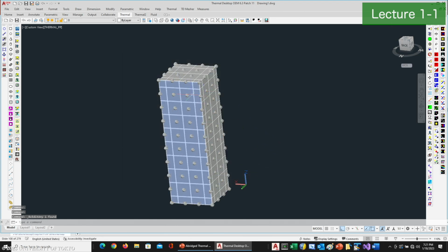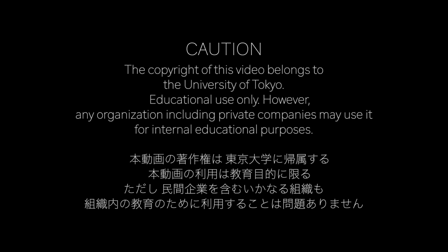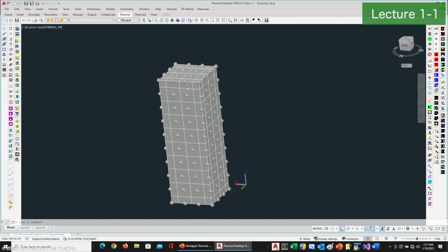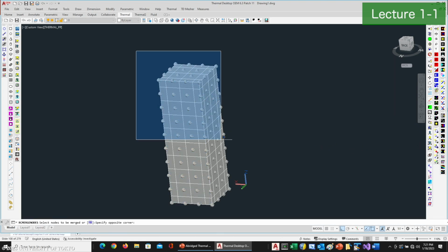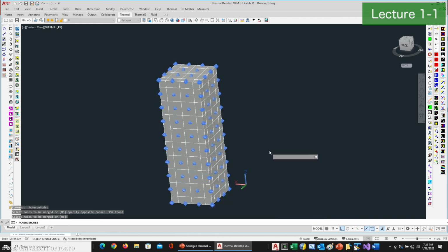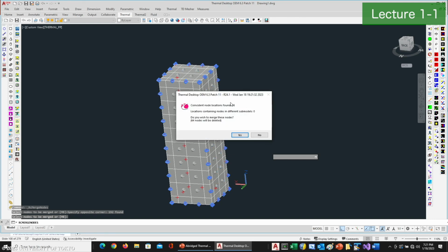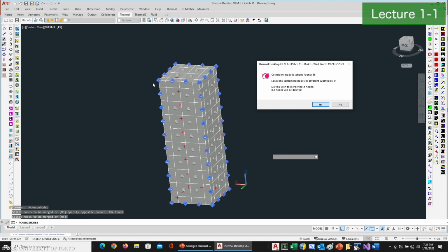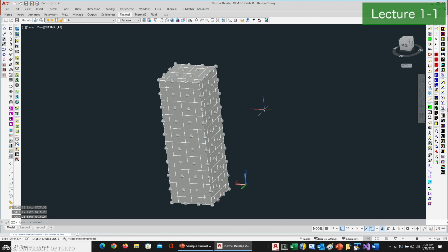So I'll get conduction from this panel to this panel via the fact that there'll be conduction between this node and this node due to this surface, and then conduction from this node to this node due to this surface, but this node is the same because I've merged them. They're the same node number, same calculation point. So that's the easy way to establish conduction in this, and so let's go ahead and merge all these nodes now. So I selected all of them, merge it, give it a minimum tolerance, and it'll tell you how many nodes it found, all the locations, and you can see right along all the edges, it zipped it up, and so now I've got those nodes merged, and so I would get conduction from one panel to the other via that.